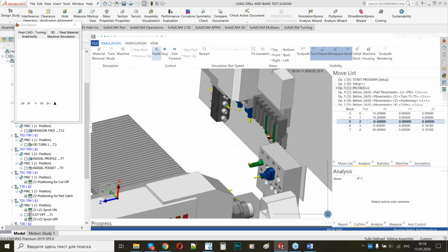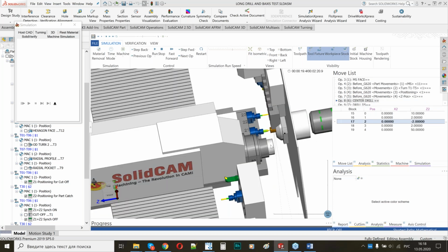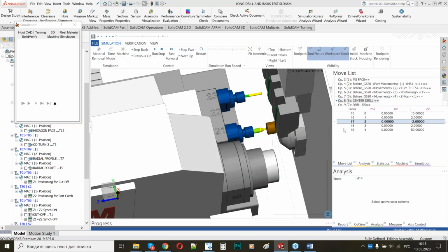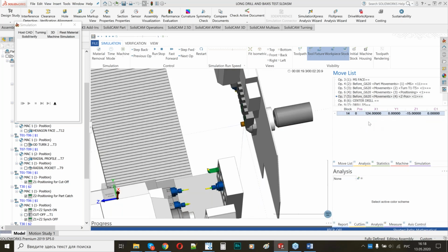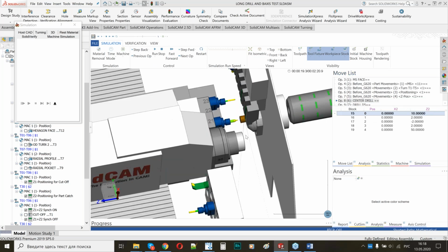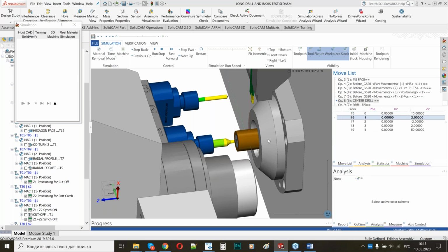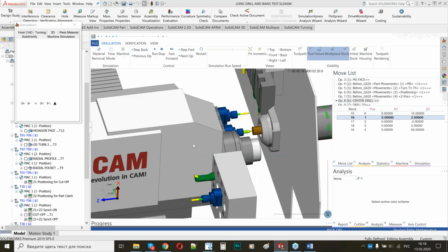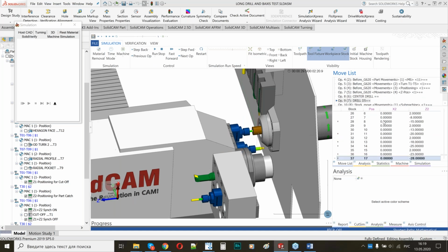I will have my space, and after that, as you can see, I have my center drilling tool. I will go a little bit back, and so here my stock is pulled out from the collet 15 millimeters. I called my T21 tool, and my stock will not move. My Z2 will move. So this is what we call a long drill operation here.